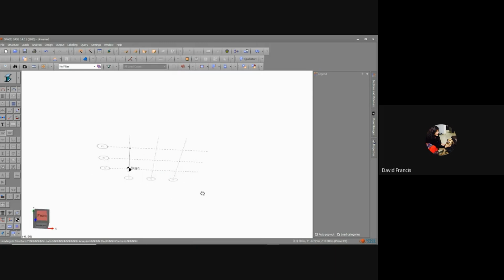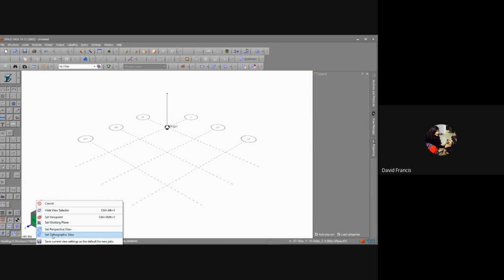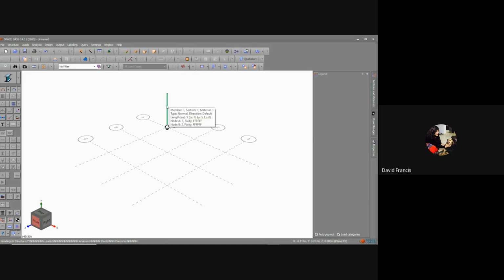All right, so just rotating and went back to where it was. You can control how you position by clicking on the cubes button, and if you right click on the cube, you've also got some additional options like the orthographic view that I used earlier. If you don't know the difference between orthographic and perspective, perspective is how we look at something in 3D, where we look around bends, but orthographic is like the plan view on the drawing board.